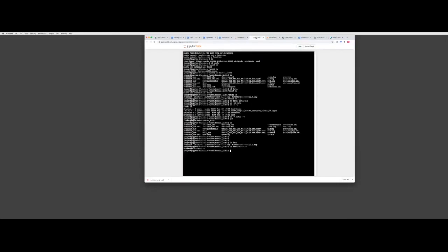So go to the topo step, and you say export OMP_NUM_THREADS=8 before you issue the stripmap command, or what? I'm typing it into the thread. That's plural, right? NUM_THREADS. Yeah. Okay, so you just precede the stripmapApp with the definition. Yeah. Okay.